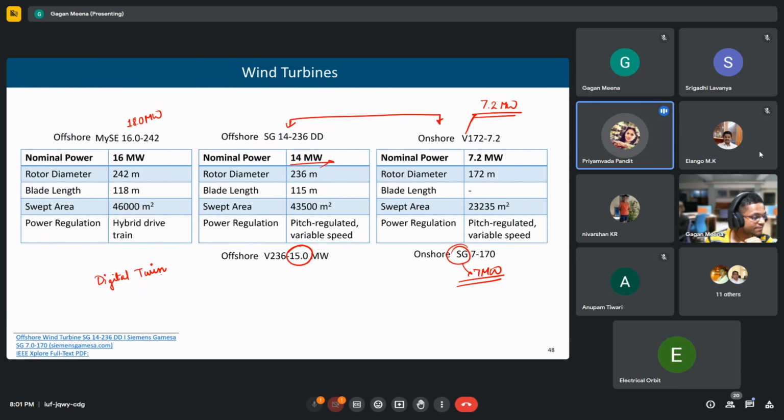In the wind turbine, when you control the power, typically what are the steps in which it can be controlled? How accurate is that for wind? Its accuracy is smooth, because we are using power electronic converters. Even control is also very smooth. It's not like fixed steps. There are not any fixed steps as such. We can have smooth control because we are using PI control.